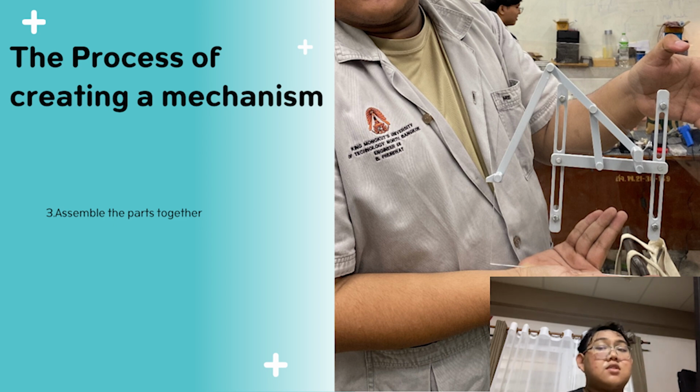Next, we will attach the output link to another section on the base link and then connect the transition link to the two previous links on the base link, placing a joint between them. After that, we will attach the working leg joint to the transition link, making sure the pin with key is placed properly, and then we will connect the foot to the working leg.